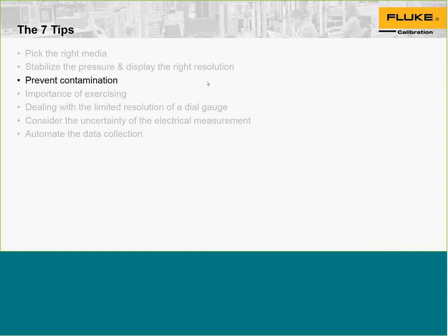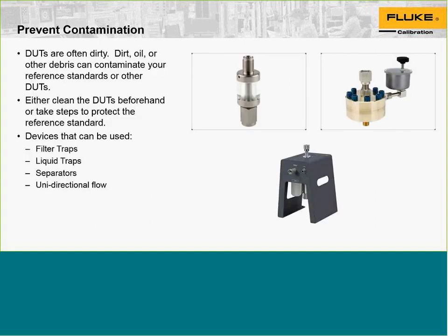Okay, so we've picked the media, we've had to generate the pressure, and we're making sure that we've got it displayed properly. Now let's consider contamination of our system here. These devices under test are often dirty, depending on the application they're used in, what process they're used in, the different dirts, oil, or other debris, and that debris can contaminate your reference standard or other DUTs.